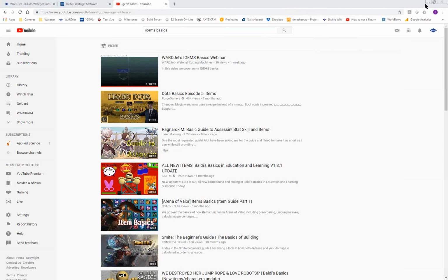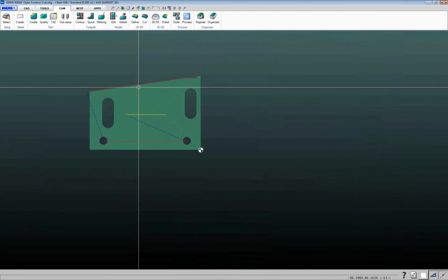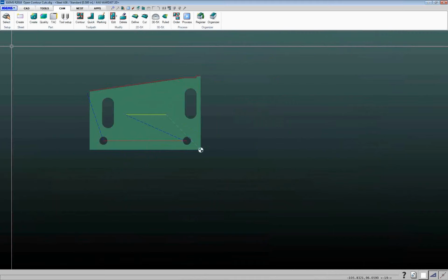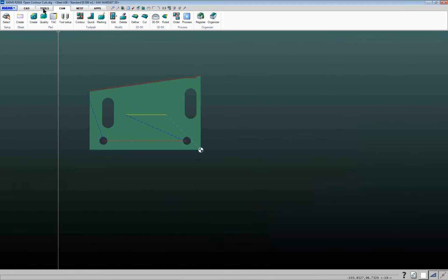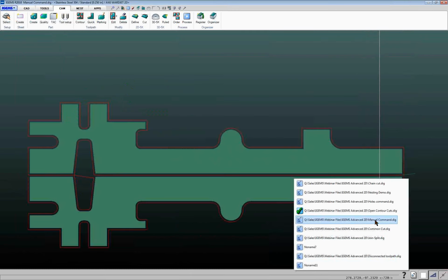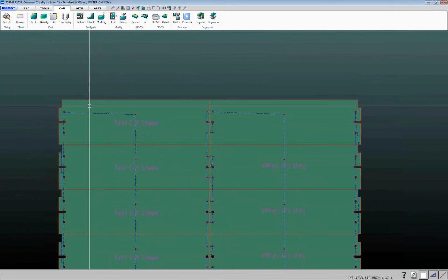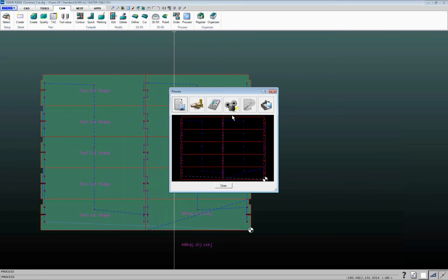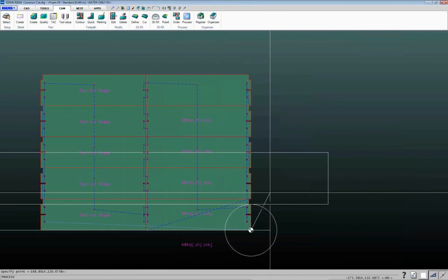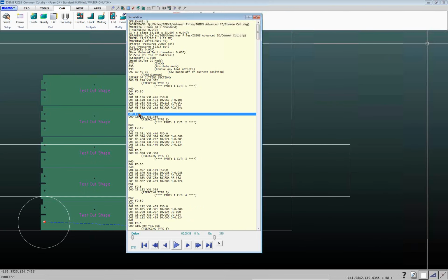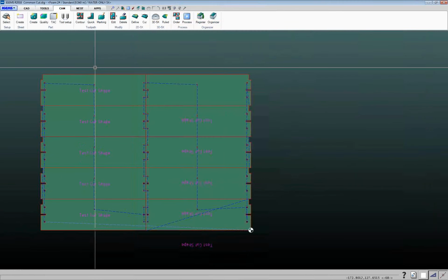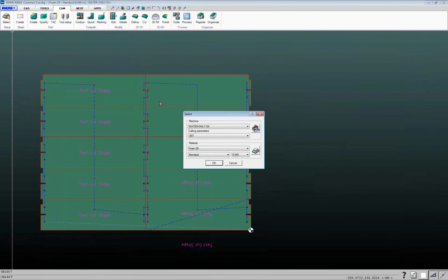Okay, if you don't need any piercing time, that's going to be controlled in your machine settings and things like that. It's two areas that control piercing time: machine settings and material settings. So assuming that we're doing this as a water-only application, let me go back to this one here. All right, so say this is a water-only application, which it looks like it'd probably be a good one. And if I go in right here and see what we've got for delays, I've got like a half-second delay after the water turns on, half-second delay after the water turns off. So if I want no delays, two areas to look.